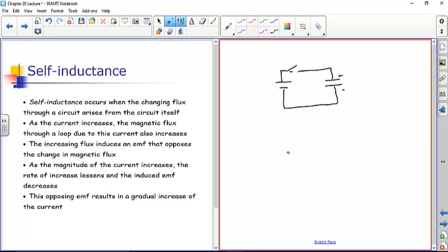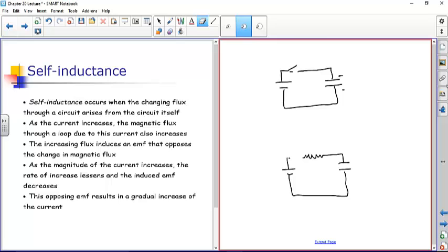The second kind of circuit we looked at was an RC circuit. So we had a resistor, and again a switch. Initially the capacitor is not charged. So we close the switch, but instead of the charge instantaneously charging the capacitor, it's going to be limited by this resistor through Ohm's law. Initially when you close the switch, the current through the resistor is determined by Ohm's law: current is equal to voltage divided by the resistance. So initially you get all the voltage drop across the resistor, and the amount of current flowing through the resistor is the maximum to start with.